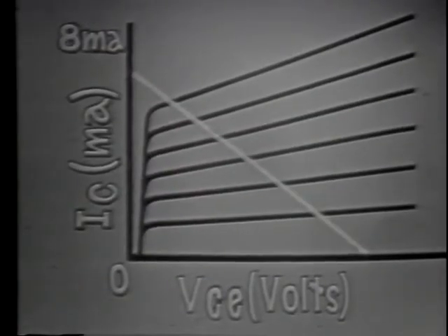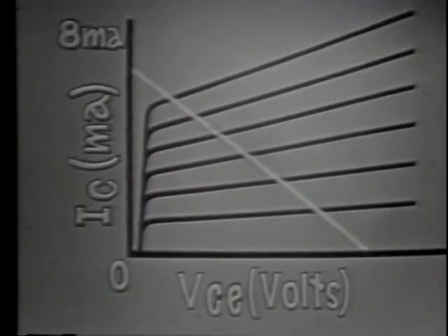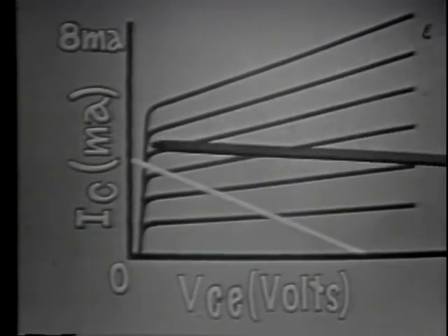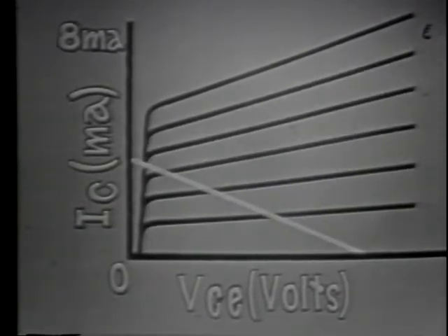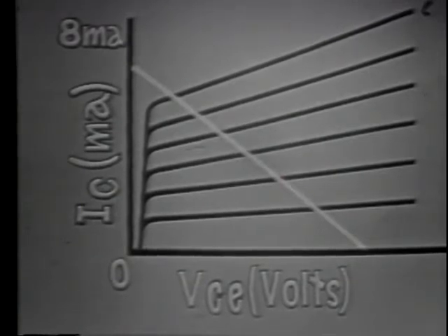We began with a small resistor and increased it. The load line dropped to here. We had a decrease in current gain and an increase in voltage gain. If we started here with a large resistor, say 4K ohm, and decreased the resistor to 2K ohm, the opposite would have happened. Current gain would have gone up and voltage gain down. An important conclusion is that a current amplifier would have a relatively small collector load resistor, and a voltage amplifier would have a relatively large collector load resistor.